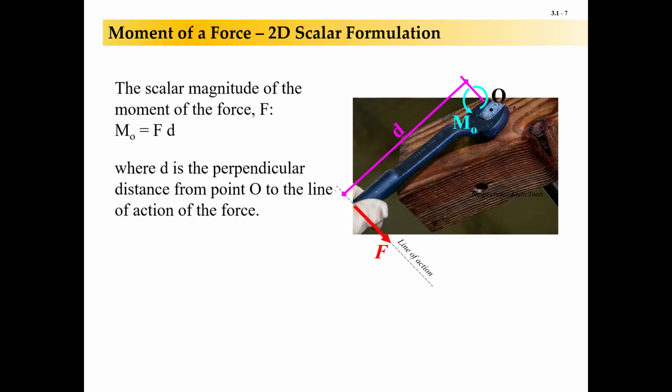And even if the force is the same, as hard as you can push, the distance is going to make that moment larger. Likewise, if you wanted to keep the same moment but work less, you could put a cheater bar on there and then just push lighter, because if the distance is twice as much, then your force would be half as much. This is the same thing that you've been studying in past courses with torque.